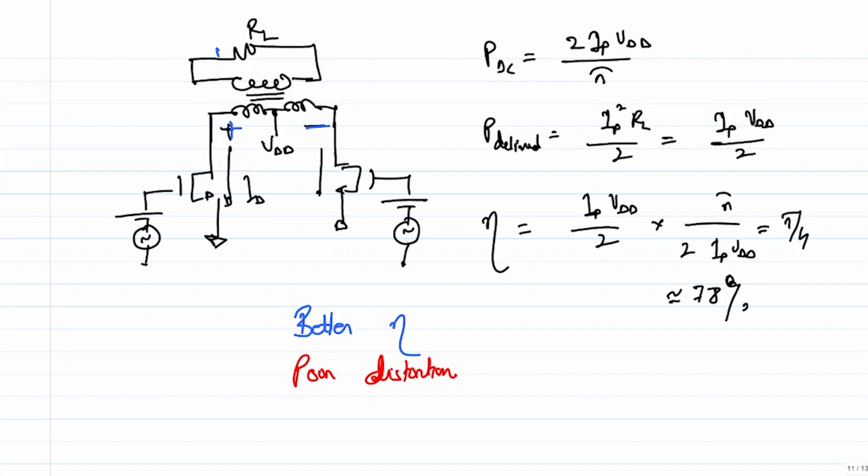So now is this an issue? This definitely is an issue. So how do we get rid of it? We get rid of it by putting filters, right? Now note that you don't have to necessarily put ideal transformers. You can put narrow band matching networks which can do impedance transformation as well as filtering, right? So instead of doing a matching network here, you can as well incorporate a filter.